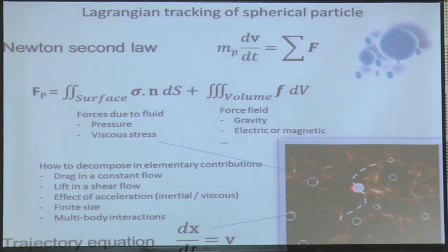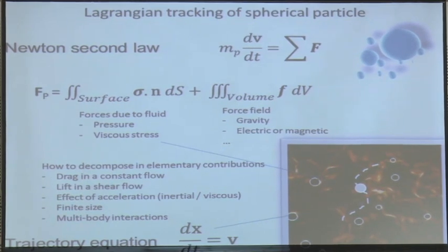And if you want to follow one particle within that flow, you need to know what are the different stress components along the surface of the particle, and then you are going to sum up all these contributions within one force. But within that force, you have all the different effects. So you have the drag, you have the lift, you have everything. So what I'm going to try to explain to you is how we can decompose all these forces as a sum of simple, elementary contributions.